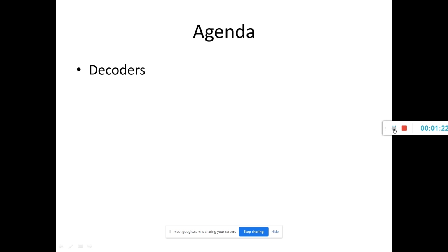We have many types of decoders. The n to 2 raised to n line decoder is a very commonly used decoder. It has n inputs and 2 raised to n output lines. Decoders have one property: one of the output lines responds with logic 1. Response means one of the output lines has a logic 1 for the particular given input combination.